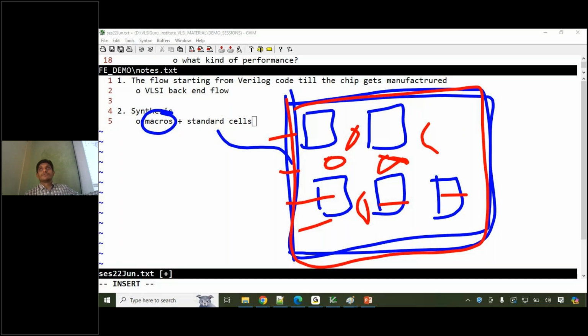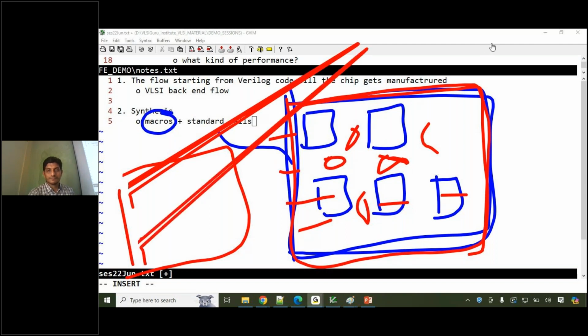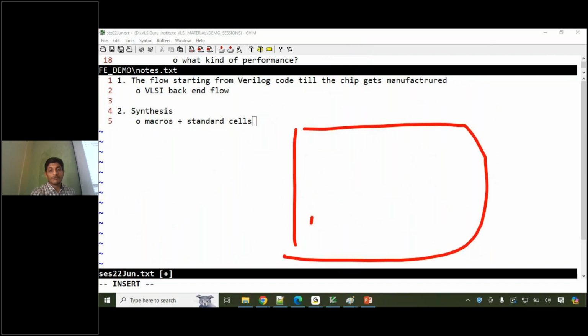Here comes the difference between ASIC and FPGA. In ASIC, you don't have any board to start. You're just starting with an empty plain area, you can now start deciding, I'll place my block here, another block here. In FPGA, you don't have such flexibility because the board is already available. You have to plan your physical design as per the board. Whereas in ASIC, because everything is empty, nothing is available, you start planning.